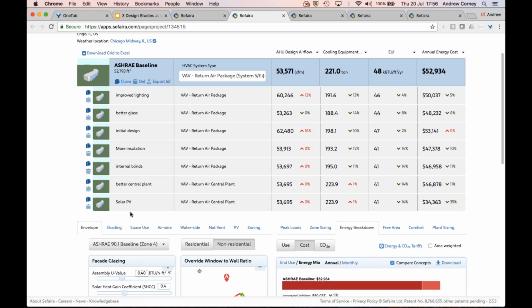All right. I think there was also a question on natural ventilation: is EnergyPlus running the bulk airflow analysis? Yes, exactly. We use the full air flow network feature in EnergyPlus, and so it does do a full natural ventilation study. We only support single-sided ventilation at the moment. We don't support cross ventilation or buoyancy ventilation solutions. But yes, it does do a proper bulk airflow analysis within EnergyPlus.